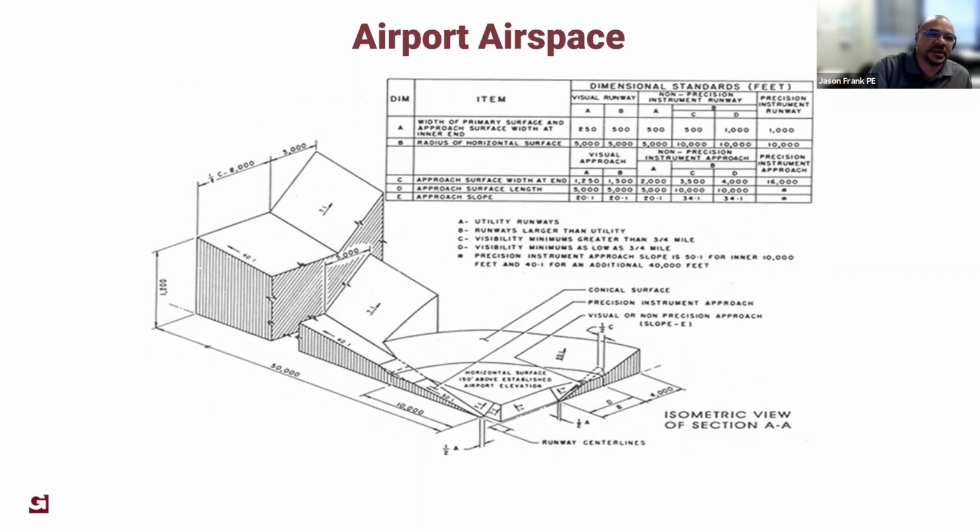So they want to make sure that space is clear of any object, any trees, any light poles, any power poles, anything like that. That's why you see this isometric drawing with these different shapes and spaces on them. It is a challenge because you're not mostly thinking of flat work. You're thinking in a 3-dimensional space when it comes to the approaches to the airfield.